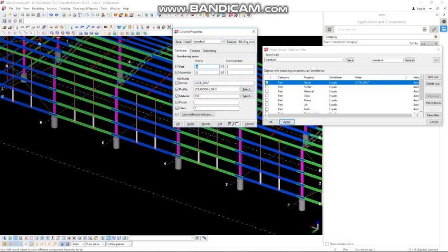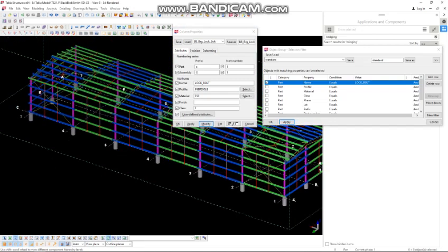So I have already saved the lock bolt for the column. So just brg lock bolt, just load this one, and as you can see, the prefix for part and assembly has been changed based on our standard, and also the name of the profile is INBR200LB, which is our standard for Stratco. And then just click modify. So we have a lock bolt. And how about the other?